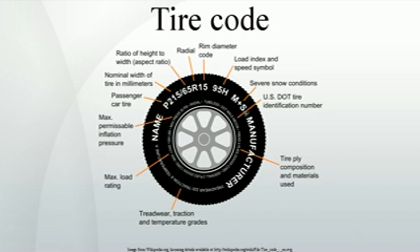ORWL, outlined raised white lettering. RWL, raised white lettering. VSB, vertical serrated band. BSL, black serrated letters. E4, tire approved according to ECE regulations, the number indicating the country of approval. 030908, approval number of the tire. DOT code.